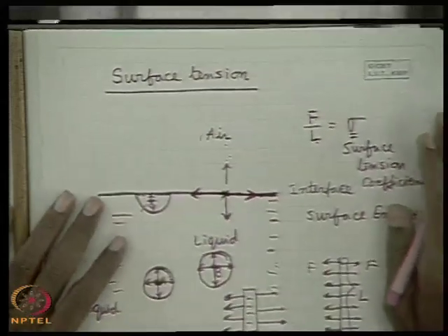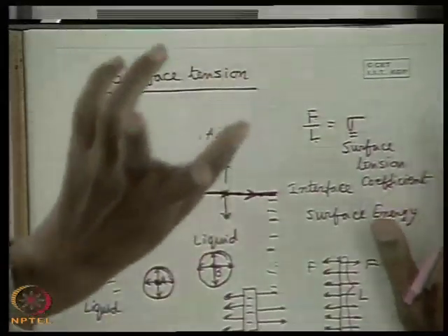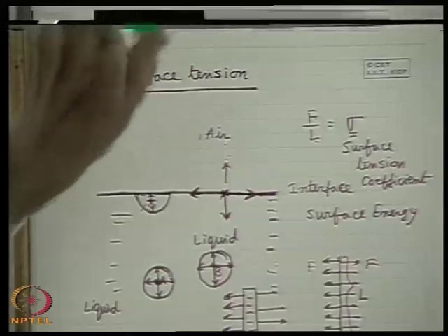Okay. Now, two very important things have to be remembered. We may not go into much detail on the surface tension mechanism, which is beyond the scope of an engineer. It is more with the physicists than with the engineers, but engineers must know the information, and two important pieces of information which engineers or applied scientists should know are that surface tension comes into the picture when there is a surface of separation between two fluids. That means a surface of separation or an interface has to be created. Without an interface, for a single expanse of a fluid, the concept of surface tension does not come.